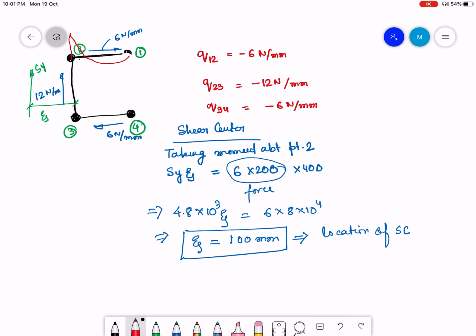It was always a function of S, and finding the shear center or working with it was much more difficult than for a skin stringer idealized configuration, where the shear flow in each portion of the cross section between two booms is constant.